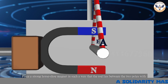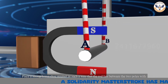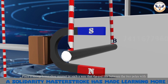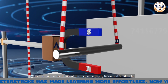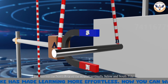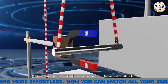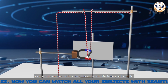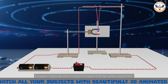Place a strong horseshoe magnet in such a way that the rod lies between the two poles with the magnetic field directed upwards. For this, put the north pole of the magnet vertically below and the south pole vertically above the aluminium rod. Connect the aluminium rod to a circuit in series with the battery and switch.